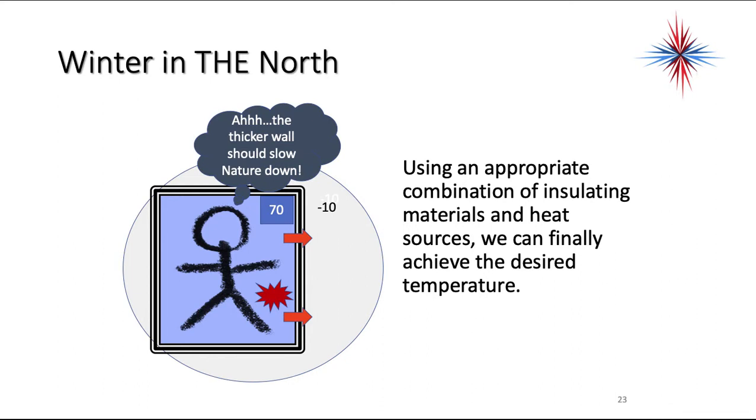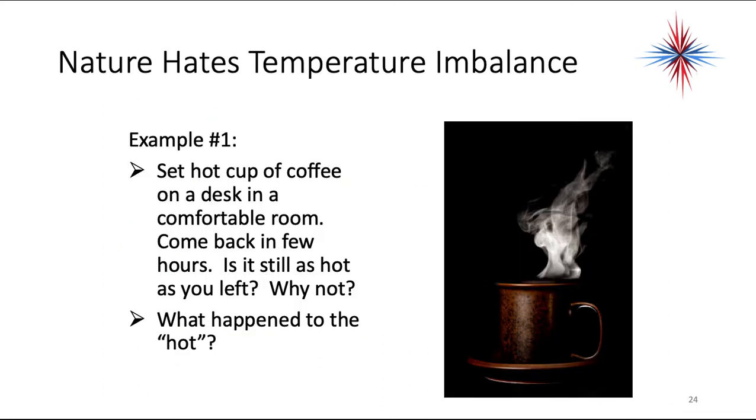If you can retain the heat, then you can reach your set points or levels of comfort without having an unnecessarily large heat source. The more insulation, the slower the heat loss, and the smaller the heat source required at design temperature. When energy in equals energy out, the temperature remains constant, and that is called the balance point.